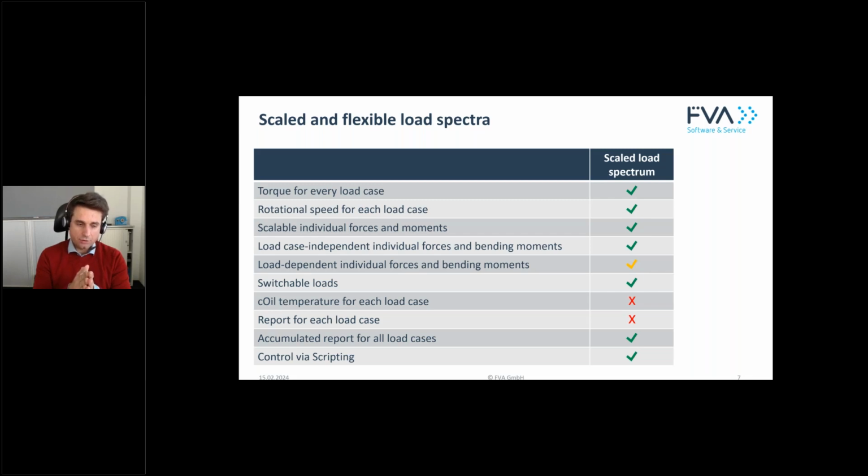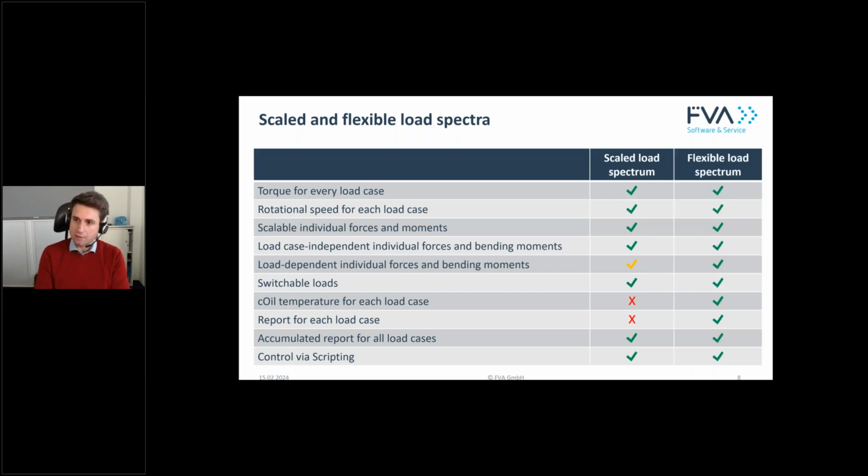However, if you would like to add additional forces or bending moments, it gets a little bit tricky. It's not possible to add lubricant temperatures or get a report for each load case. And we fixed that with what we are calling flexible load spectrum. With the flexible load spectrum, you can take all these effects into consideration.